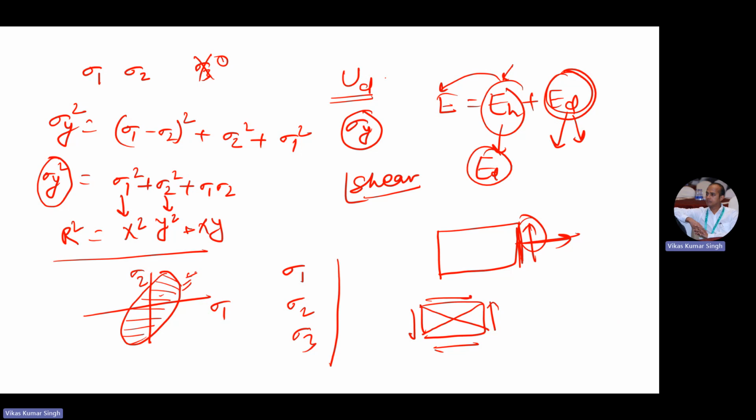So the thing is, what is the maximum value of the tensile stress in this plane and in this plane, these two. Okay, so if you put all this condition, your sigma 1 and sigma 2 will be equal, with the minus. In this direction there will be tensile, because we are putting a stress in this direction, and in this direction, and this will be compressive.